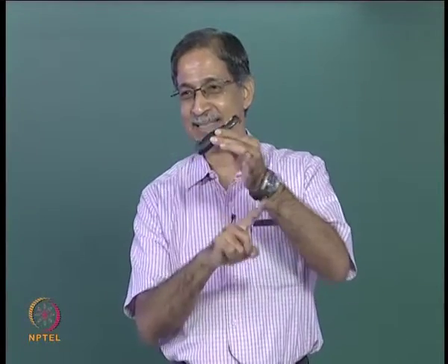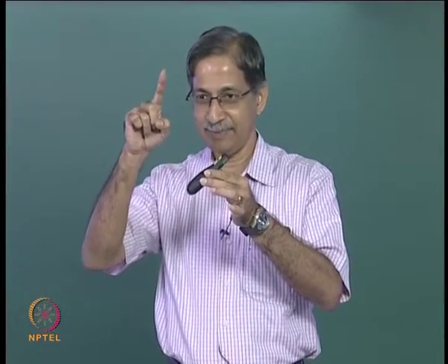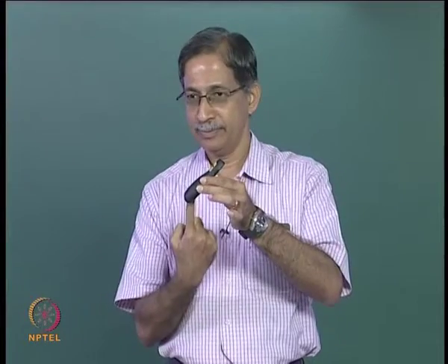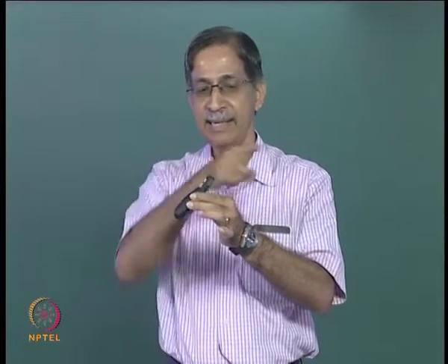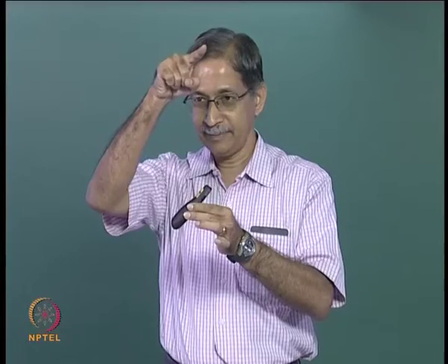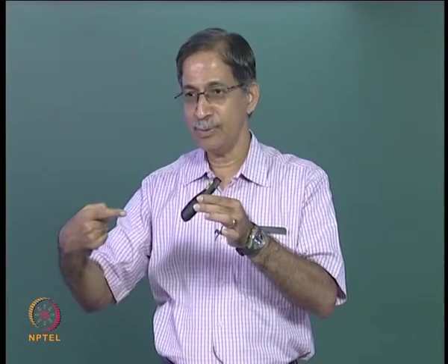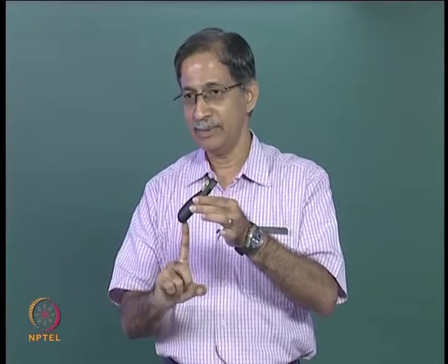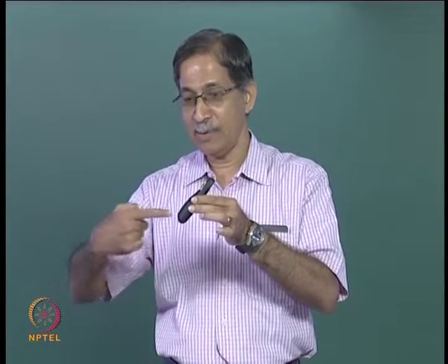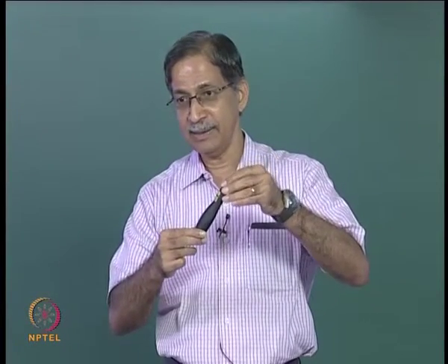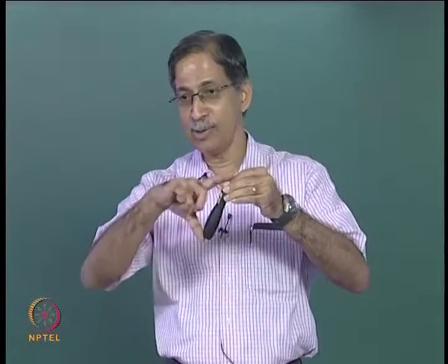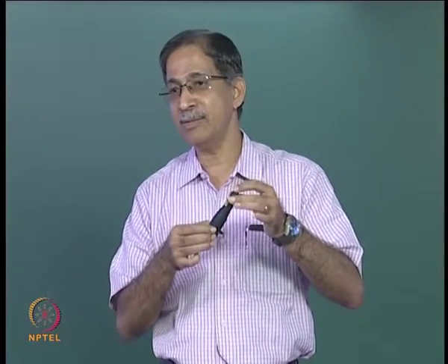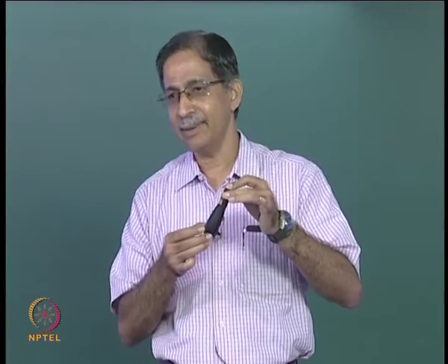So this was your x axis, this was your y axis, right, and your coordinate was 1 and 2, and you had coordinate 3 and 4, right. Now we want to know what happens when I apply d1 equal to 1 to this element and d2 equal to 1. Do you agree? When I apply d1 equal to 1 and I prevent d2, this is going to reduce in length because I am pushing it. So will I get a positive elongation or a negative elongation?